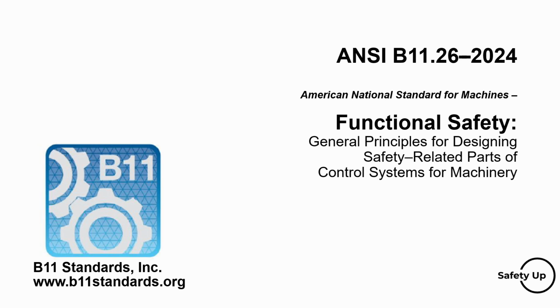The Fault Considerations section addresses the evaluation of failure modes that could affect a specific circuit's ability to perform its safety function. It includes common cause failures, fault exclusions, and specific failure modes for electrical, fluid power, and mechanical components. The Monitoring and Diagnostic Coverage section emphasizes the need for monitoring and diagnostic coverage to ensure the reliability of safety-related control systems. It provides methods for electrical and fluid power monitoring, including direct and indirect monitoring and monitoring by the process.